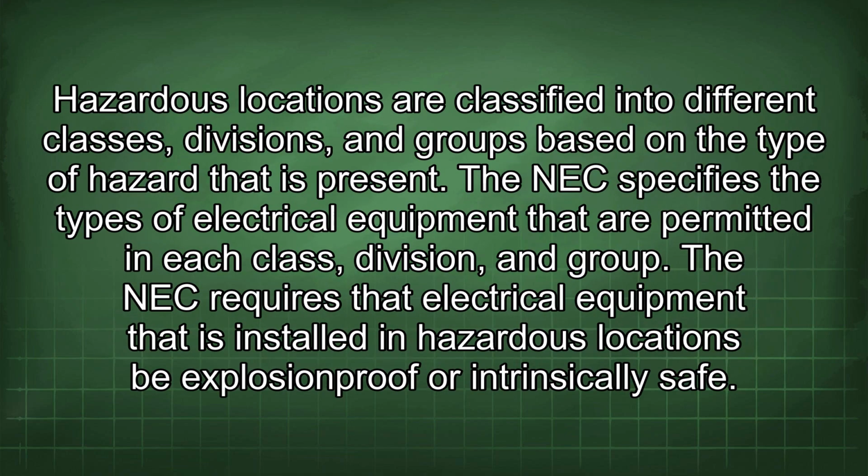Hazardous locations are classified into different classes, divisions, and groups based on the type of hazard that is present. The NEC specifies the types of electrical equipment that are permitted in each class, division, and group. The NEC requires that electrical equipment that is installed in hazardous locations be explosion-proof or intrinsically safe.